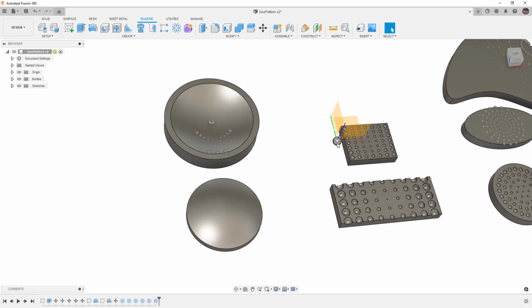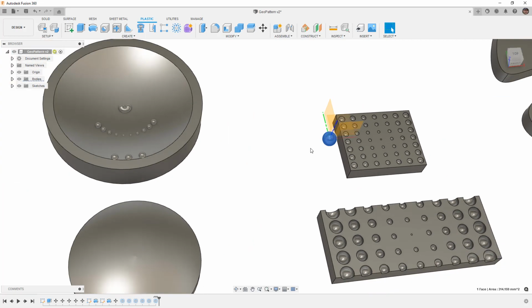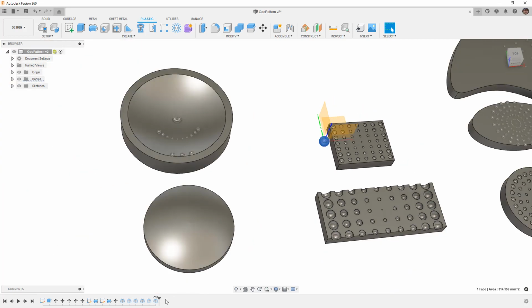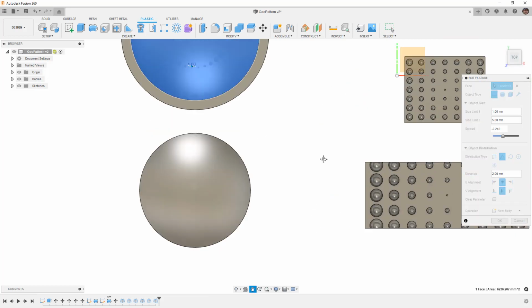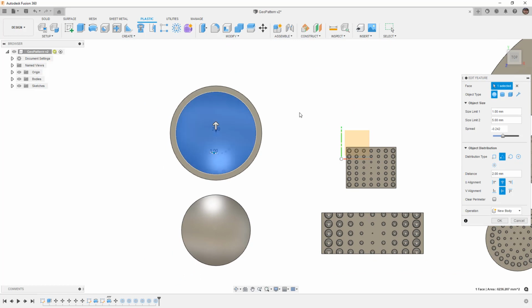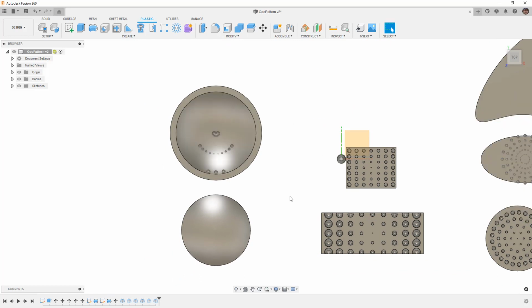And also note that it did put the sphere here at the origin. And if we look at that, that sphere is actually part of this. So another interesting thing is, again, with that initial example, that offset value was based off of the coordinate system. So that is something that we need to be mindful of if you tend to move your designs away from the coordinate system. In this case, I drew them just sort of all over the place, but having the coordinate system be over here could be a potential problem.